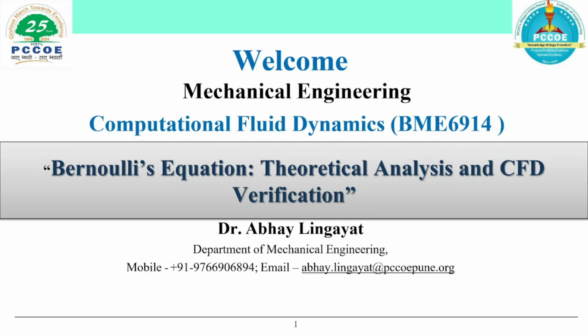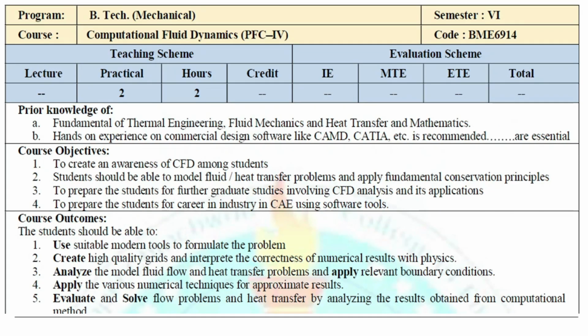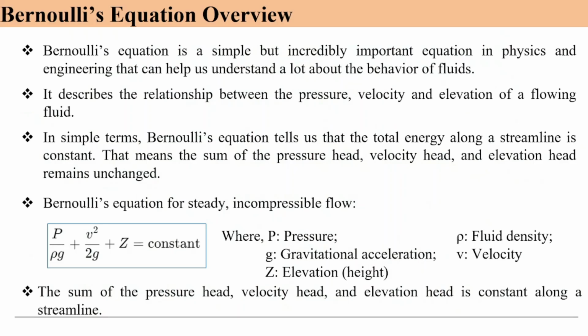So let's start. Bernoulli's equation is one of the most fundamental principles in fluid dynamics, widely used in physics and engineering. This equation provides insight into the behavior of the fluid by establishing a relation between pressure, velocity, and elevation within the flowing fluid. Bernoulli's equation states that the total mechanical energy of an incompressible and non-viscous fluid remains constant along a streamline. That means the sum of the pressure head, velocity head, and elevation head remains unchanged.